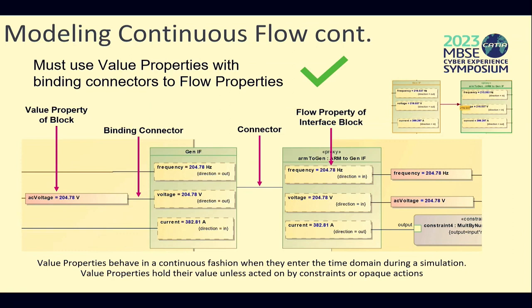And let's say you had a few things that were typed as the same thing. What it will then look at is the names of those flow properties. So it first looks to update the same thing with the same type on the other side. And then if there's multiple things with the same type, then it'll look at the names and know what to update across that connector path.